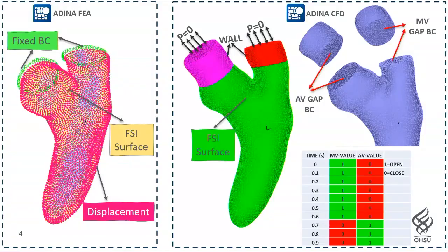It generates a connection between one fluid domain and another fluid domain, and it's controlled with a time function. When the time function is 1, it allows the fluid to flow from one domain to the other. If it is 0, it closes the connection between the domains. It simulates the opening and closing of the valve. Of course, it's not going to be the exact valve opening. It's going to be a sudden opening and then a sudden closing. You can also see that effect in the flow.